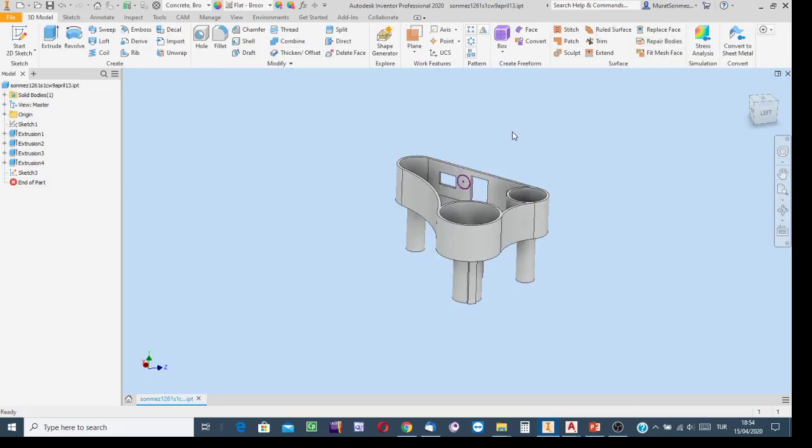And then say my purpose is to create the empty space, not here, but there. Is it necessary to use a workplane? No, because I found an existing flat surface. I took a sketch right on it. But the cutting won't be over here. The empty space is to be created over this curved part. Since it is impossible to draw a sketch right over a curved surface, I drafted the sketch over this flat surface and then see the rest.